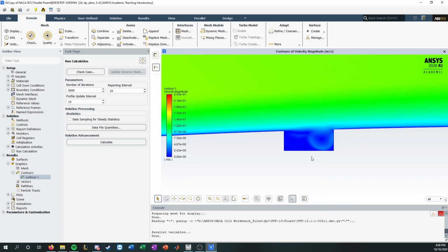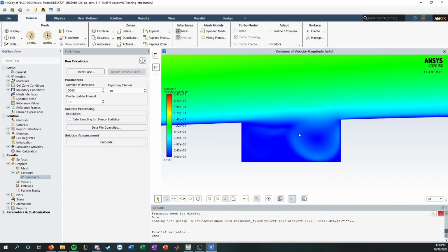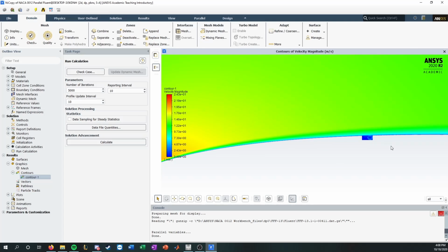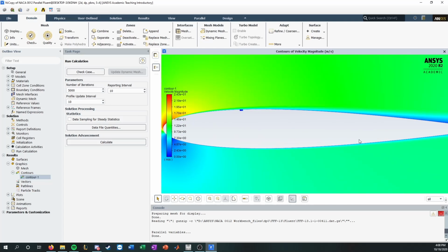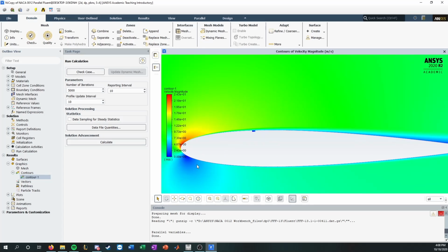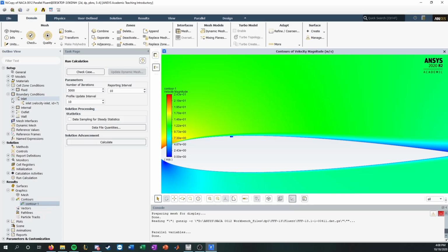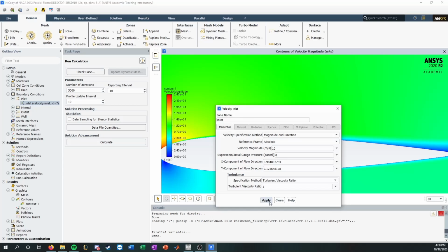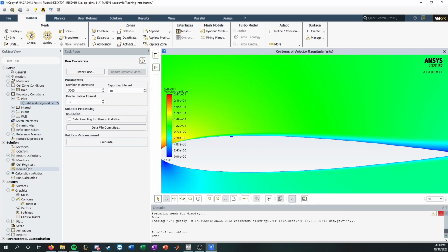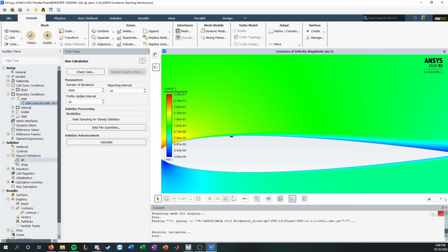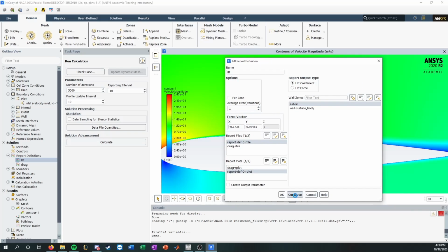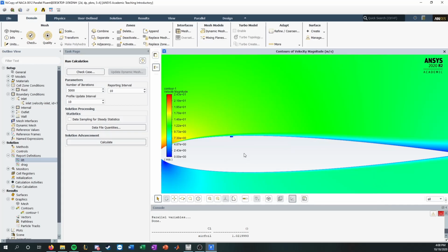However, I saw this. This is the stereotypical recirculation zone. Flow would come in, get trapped, and it didn't show the energization of the boundary layer. And this was at, I believe, 4 degrees angle of attack. Yeah, 4 degrees angle of attack. And I basically saw slightly less lift and slightly more drag. So once again, oh no, this is 10 degrees angle of attack.